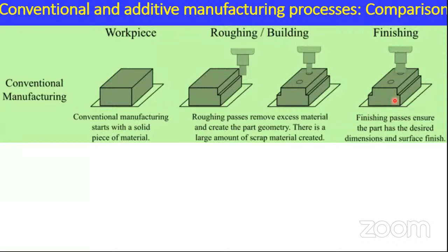application part. The time taken is quite long, because of the fact that you need to move from, let's say, one position to the other position. Maybe in the case of CNC it might be happening in the single machine itself, but in the conventional route, if you recollect, if we want to make it with the milling machine and then moving into a drilling machine, so the alignment issues, associated fixtures, time taken, all those things play a greater amount of time.